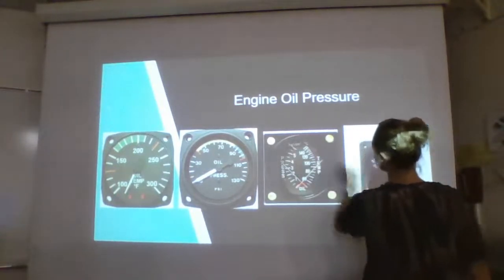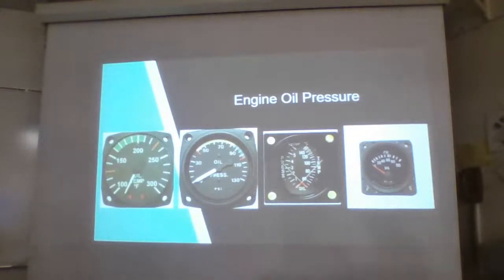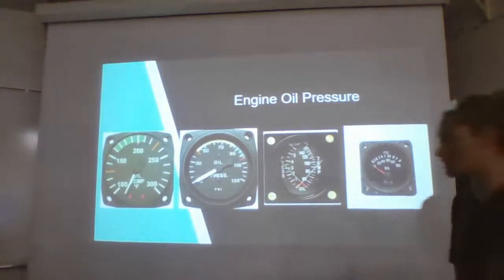your oil pressure range. So again, a pilot or a maintainer needs to know what those ranges are when you're running up engines to do ops checks or functional checks for any components that we've changed. You need to know the operating ranges of these things so that you know if you have an over temp condition or maybe your engine oil isn't building any pressure, because that could be a big problem. And then another one over here, an older version, basically goes 0 to 100 PSI. Again, you need to know what that operating range is.